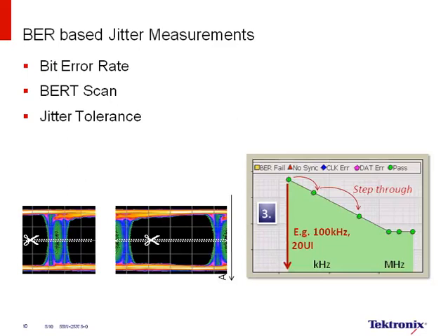But how do you characterize receiver jitter? Well, for the longest time, if you look at the specs available today, you see words like TP4, jitter characterization, receiver characterization. Essentially, what you do here in these standards is you actually look at the input to the receiver. Fact is that these are really not receiver testing or receiver jitter. These are what's known as far-end transmitter eye testing.